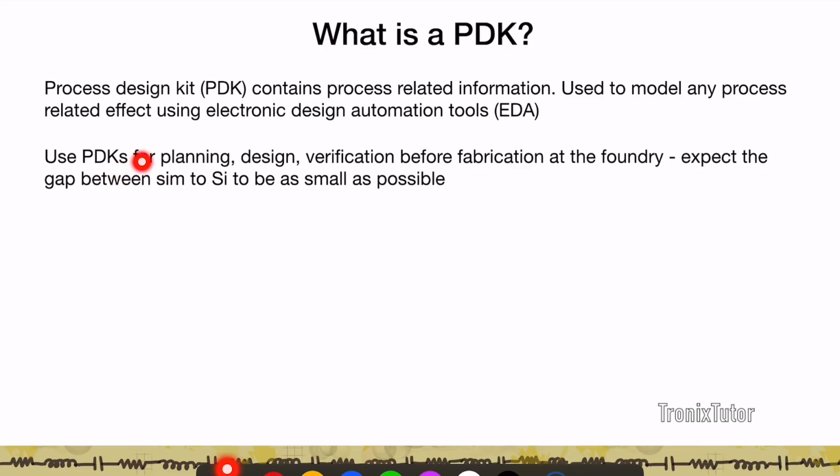Now, PDKs are used for planning, they're used in design, and they're used in verification. And all this happens prior to fabrication, right? So typically, if you look at the timeline of products, this happens probably a year or two prior to actual tape out at the foundry. And the expectation from a design house, suppose you're doing a design, is that this initial pre-work you're doing prior to taping out the design